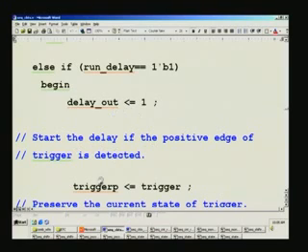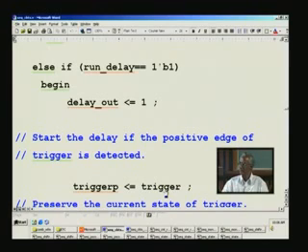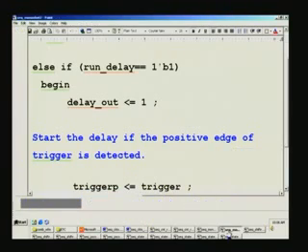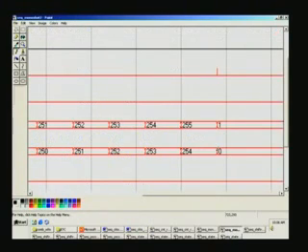The reason being that when it touches 255, in this case you would have very easily seen that 255 clearly for one complete cycle. In this what we had seen here is 254. In the previous case, had you implemented that one, instead of after 254 it won't become 0, it would go to 255 and next only it will go to 0, because counter reg is activated in the present clock cycle, which will be taken into consideration only on the arrival of the next clock. So in other words, in the previous design it has to wait for the next here. Are you clear about this? Thereby 255 plus the 0, that 0 remains same.